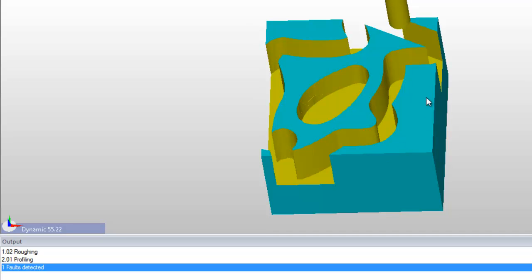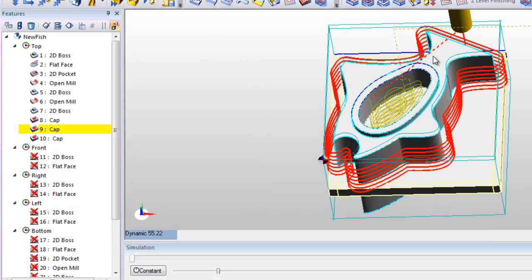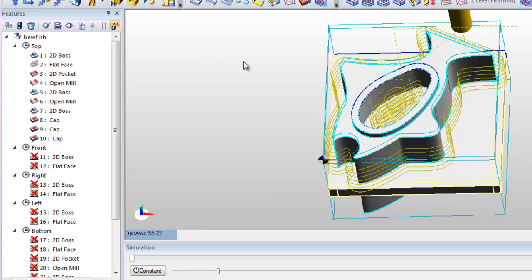So I didn't need to take out all that material, because eventually we're going to be cutting with the bandsaw just right here at the bottom, and all that excess material will fall off. So the profiling just cut out what we needed, left the rest here, and it saved us some time and some wear on the bit. So far so good. Hit X, and now the last thing I need to do is mill out that lip.